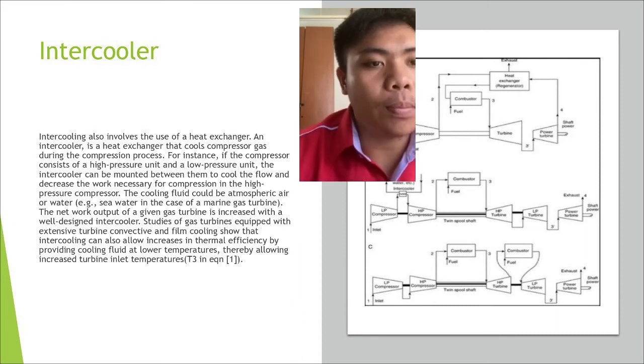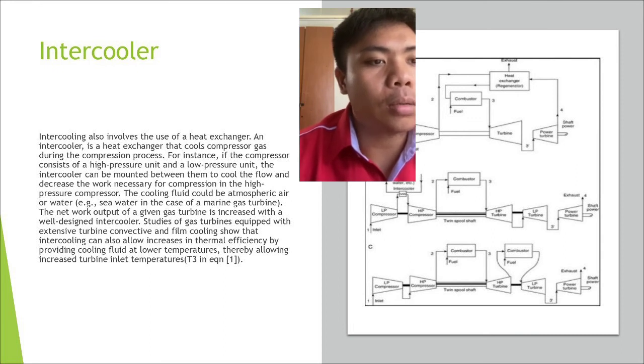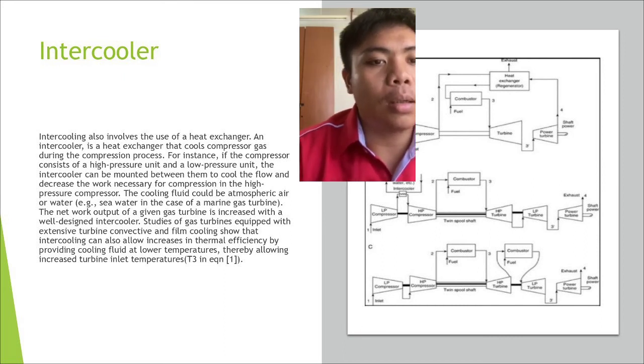Studies of gas turbines equipped with extensive turbine, convective, and film cooling show that intercooling can also allow increases in thermal efficiency by providing cooling fluid at lower temperature, thereby allowing increased turbine internal temperatures.